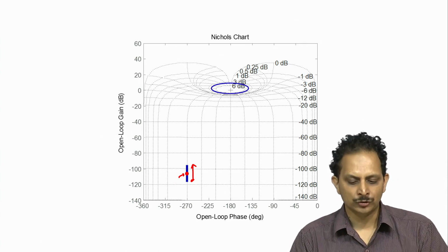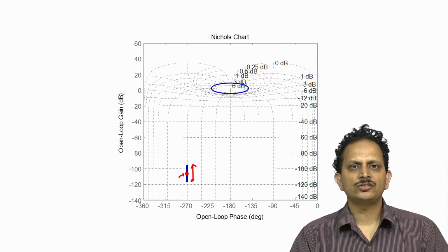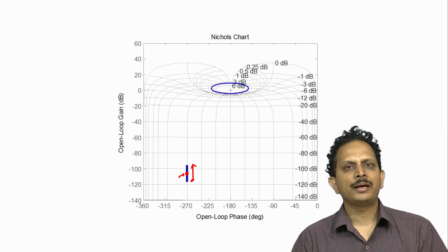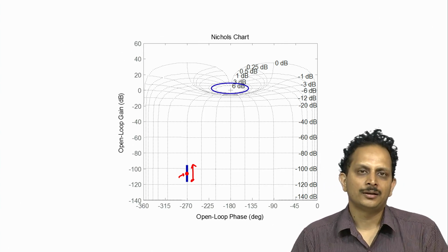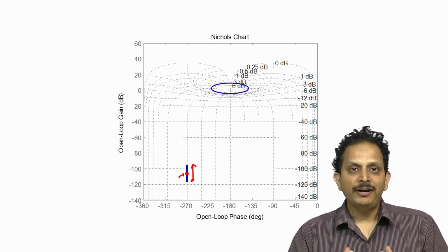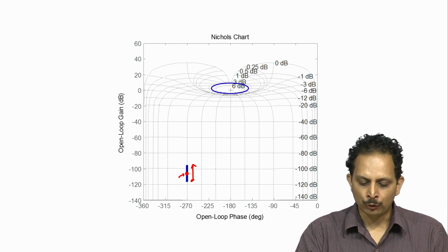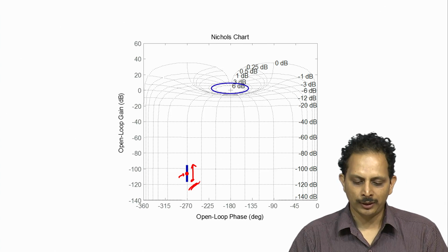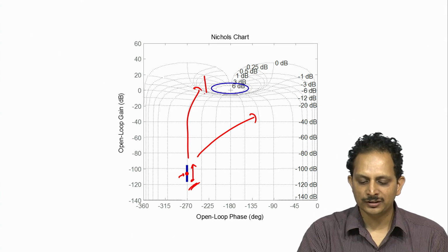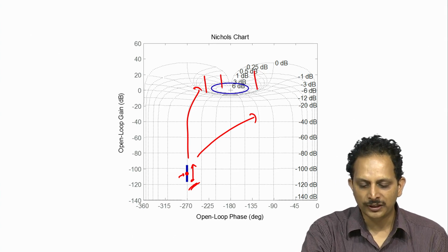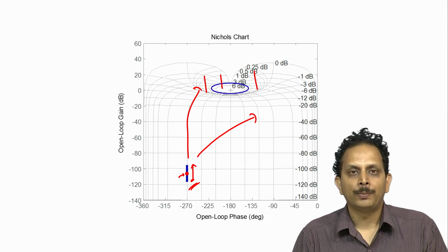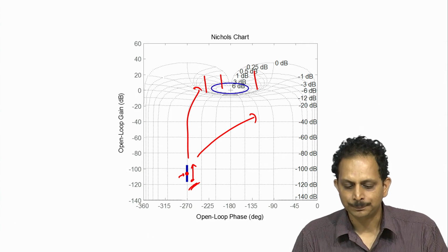The reason that it reduces to a straight line is because at very high frequencies the phase lag added by all the terms of the transfer function end up reaching their ultimate values. So when we design a controller, this plant template will no longer be located where it is situated now, but it could move anywhere in the complex plane. So it could move here, for instance, it could move there, it could move here and so on and so forth. It depends on the gain of the overall open loop system at that particular frequency.